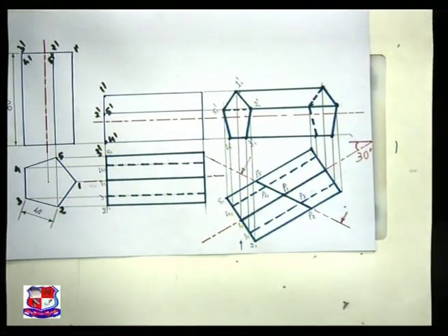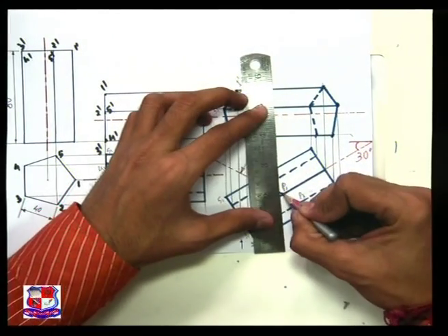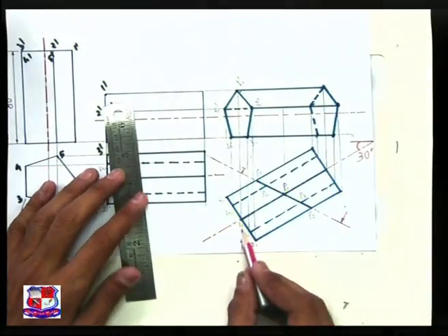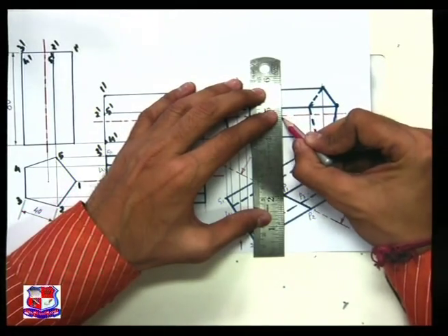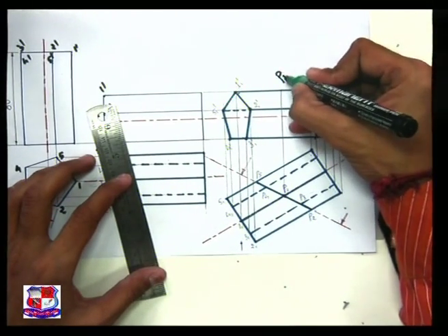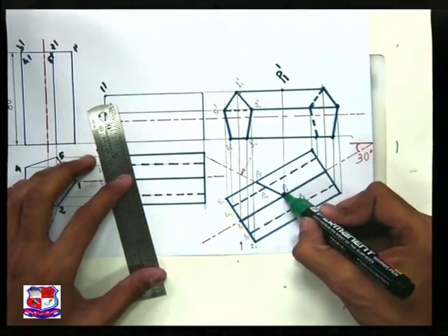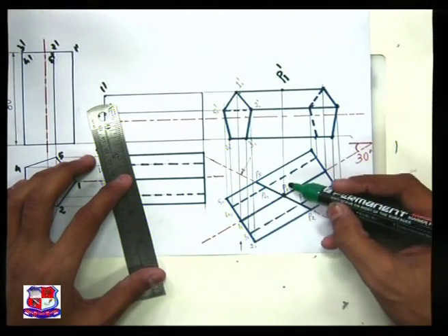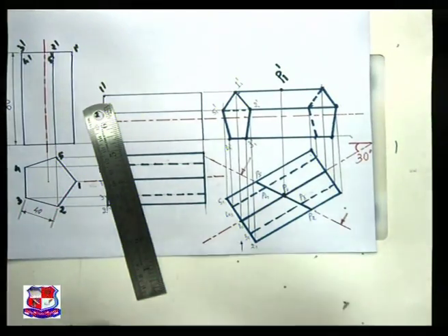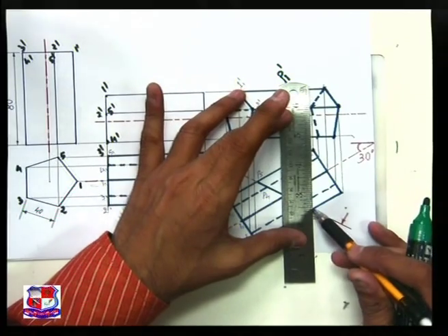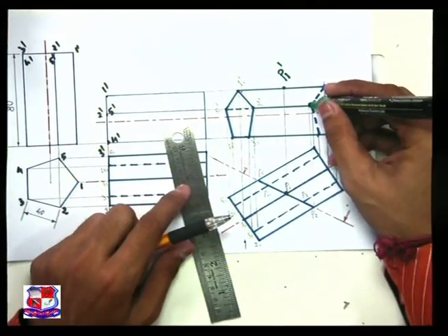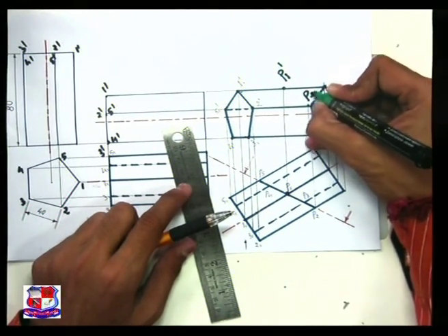Now transfer all these 5 points to the front view, vertical line from point P1. So from here up to 1, draw a vertical line here. So here would be point number P1 or P1 dash, right? P1 is here on generator 1 1. So from here draw a straight vertical line, and on 1 1 it is point P1. Similarly point P2 is here. So from this point draw a straight vertical line, and on 2 it is somewhere here point number P2, name it as P2 dash.